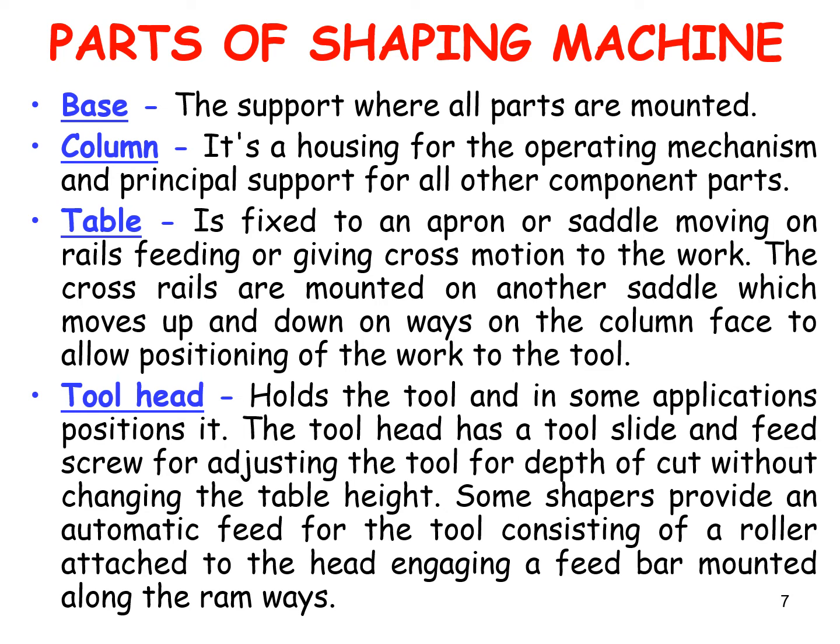Tool head: holds the tool and in some applications positions it. The tool head has a tool slide and feed screw for adjusting the tool for depth of cut without changing the table height. Some shapers provide an automatic feed for the tool, consisting of a roller attached to the head engaging a feed bar mounted along the ram base.